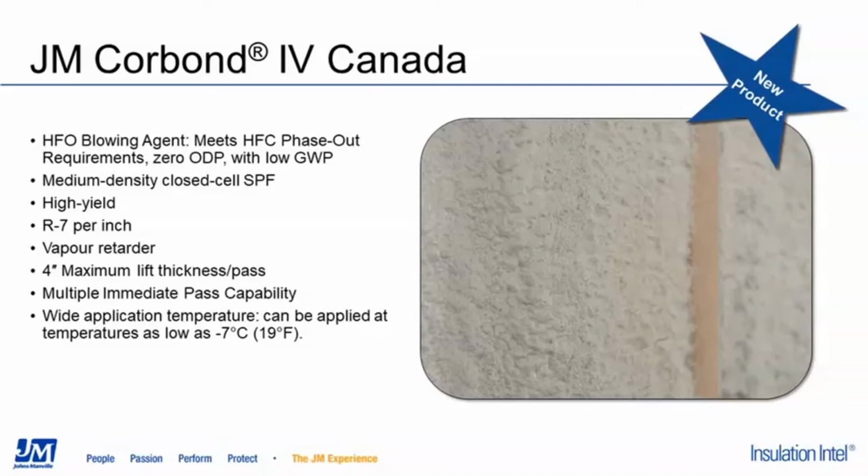But up in Canada, you're only allowed at this point in time to do a 2-inch pass. But we can do multiple passes because our product doesn't burn, so you can do them immediately. Typically with a spray foam, for every 2-inch pass, you would have to wait 20 minutes to come back and spray over that. That's not the case with Johns Manville product.